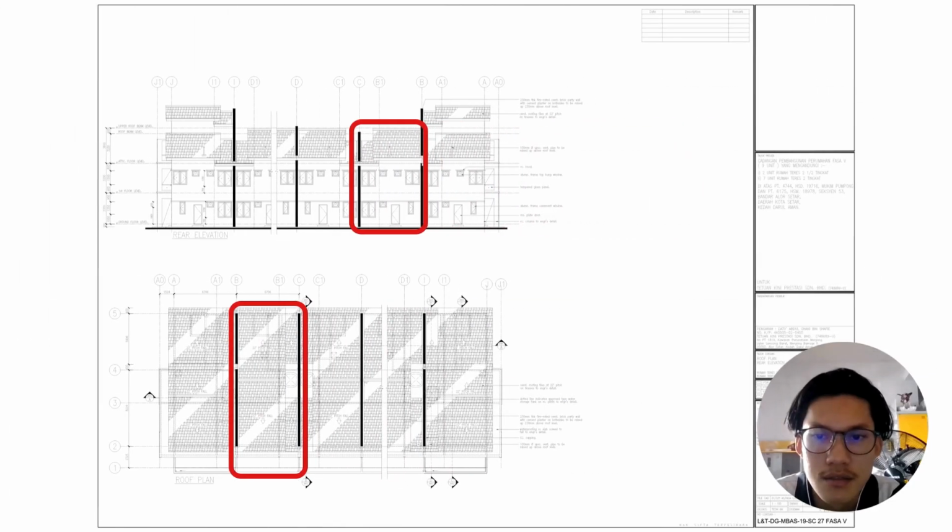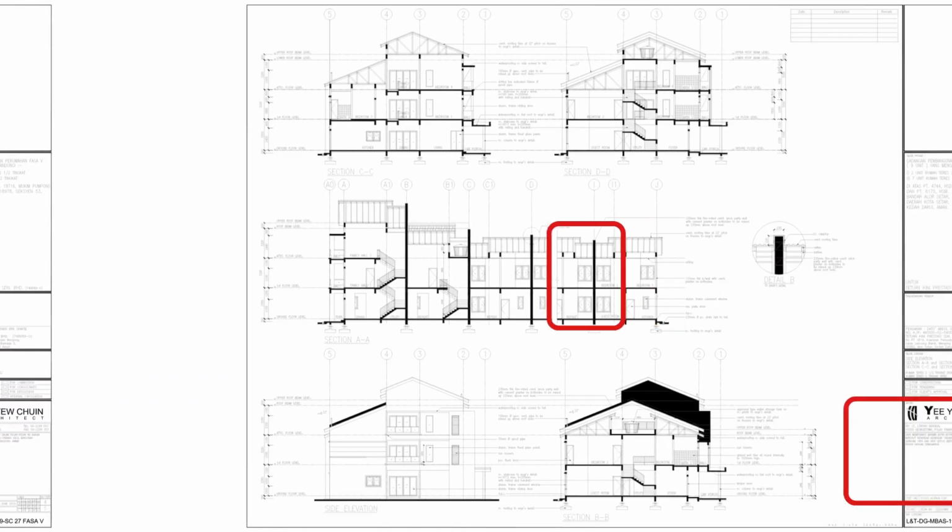Next slide is the elevation plan for the rear view. In this slide, it shows only the view of the middle terrace house. It is because as a middle unit, the side elevation are shared with the adjacent houses, which reduce the external wall construction. So this allows IBS wall panels to be designed with uniform opening and finishes and improving consistency across the terrace row.